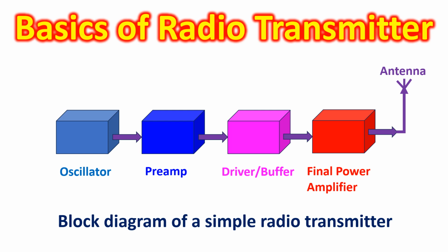Oscillator section was called a VFO, or variable frequency oscillator, as the frequency could be varied within the amateur radio band using a tuning circuit with a fixed value inductor and a variable capacitor. Single frequency crystal oscillators were also there, which had high stability as the frequency depended on the vibration of a quartz crystal, which would be constant at a given temperature.